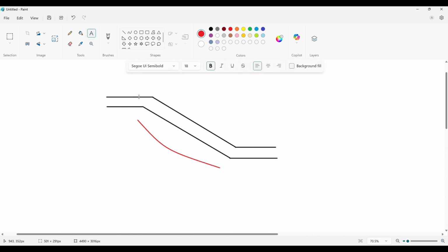Okay, generally we have a hidden beam over here, or we'll have a plinth beam over here, whatever is the case, we'll have a support there. So this zone comparatively will not control much tension compared to the mid portion. Okay, this complete flight will be suspended by this portion and this portion, right? So the tension will come over here in this zone. Okay, so tension will be here. Let me just type it a bit closer. Okay, so the tension zone will come over here in the flight of the staircase.